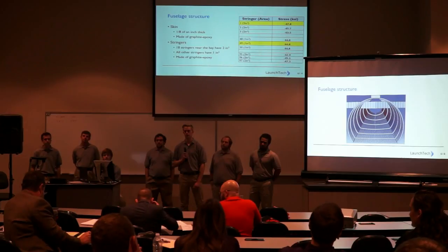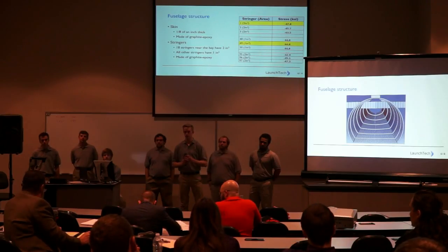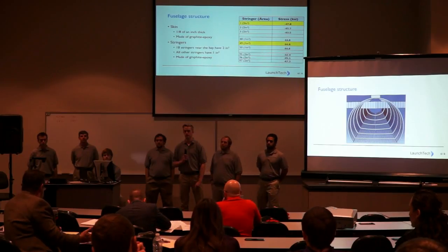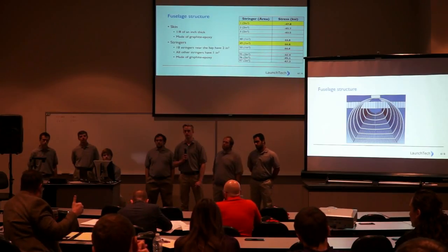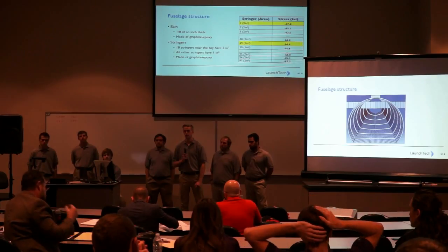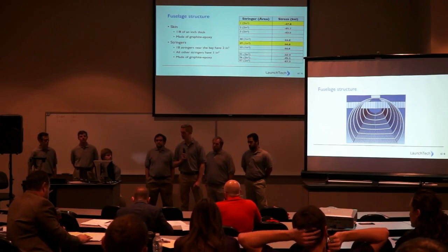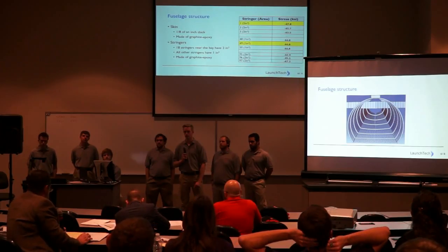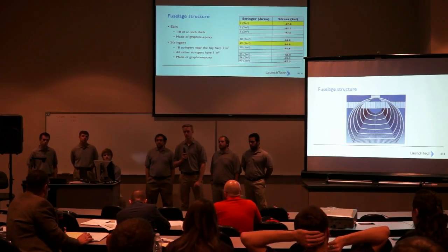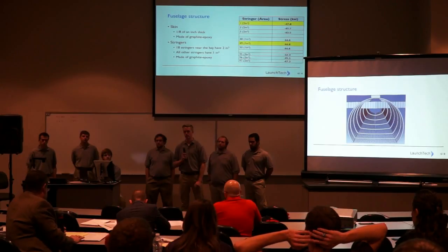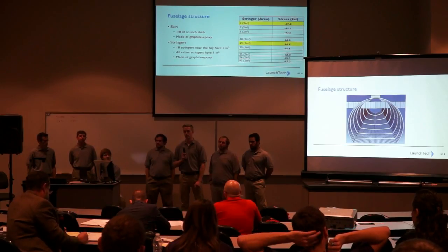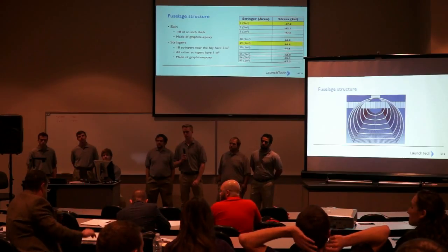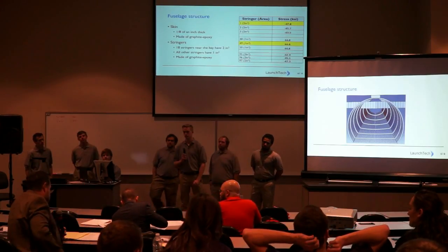I also had questions about your takeoff distance, your refused takeoff. What if you have to bring the payload back? Even if you can retract it, that's going to make your weight go up. I'm not sure your landing speed accommodated that. You kept saying high temperature, if this is a subsonic airplane. I really don't know where there are going to be any high temperature problems in this operation concept. I really don't.